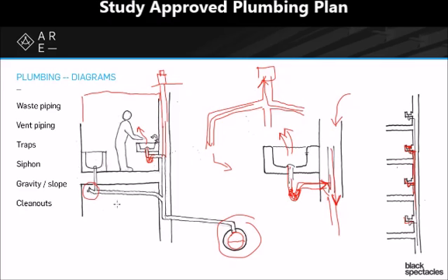This may not seem like a big deal, but if you have a clean out, it also means you have to have access to the clean out, which means that there has to be an access panel if it's not readily exposed into the room. If it's hidden behind drywall, there has to be an access panel. Well, if that happens to be in the middle of your main lobby or in the living room or in the conference room or something, that can be a big deal. So thinking about where those clean outs go, thinking about how the system's going to work, is actually kind of a design decision, even though it seems like it's only a systems decision. So that's one of those kind of unusual ones you have to be a little careful about.